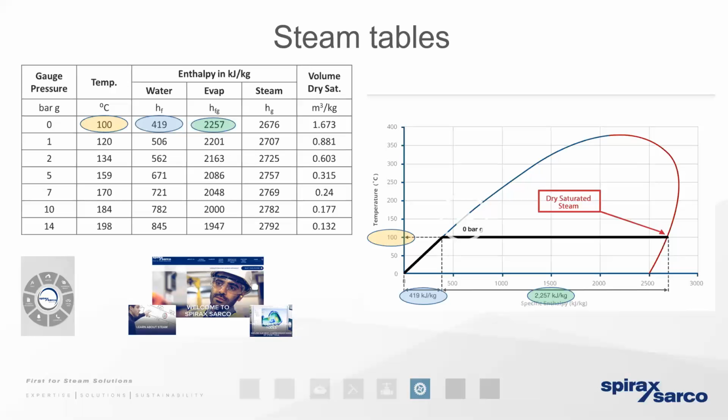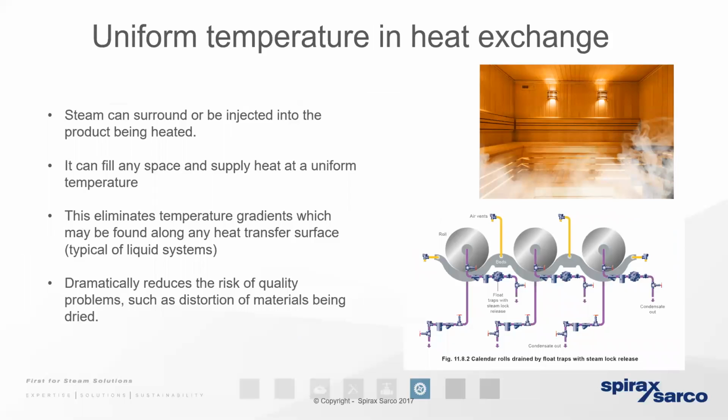So we also know that apart from those very valuable fundamentals that make steam a very attractive source of heat energy, remember, steam's got in many cases up to 50 times more heat energy per kilogram when compared to low temperature hot water. Remember, steam gives up its heat energy evenly and equally across the heat transfer surface area. And remember, there's a speed of heat transfer that is approximately 3 times that of low temperature hot water, for the simple reason that steam gives up its heat energy by condensing.